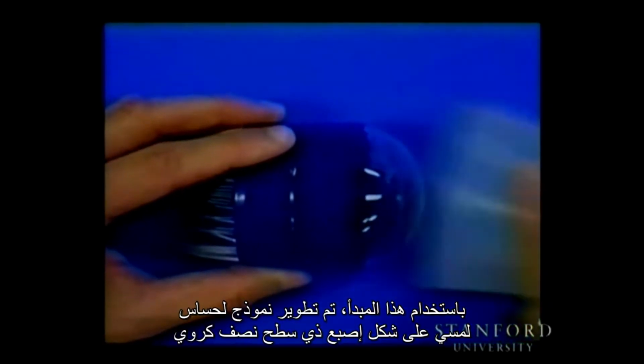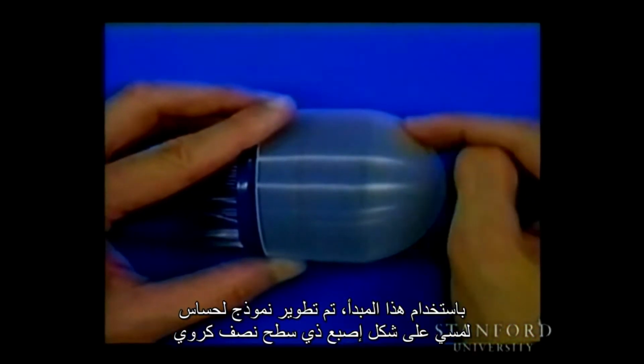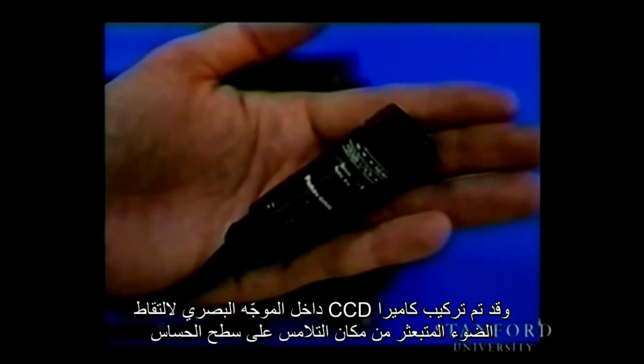Such tactile information can be converted into a visual image. Using this principle, a prototype finger-shaped tactile sensor with a hemispherical surface was developed. A CCD camera is installed inside the waveguide to detect scattered light arising at the contact location on the sensor surface. The image from the CCD camera is sent to the computer, and the location of the scattered light is determined by the image processing software. Using this information, the object's point of contact on the sensor surface can be calculated.